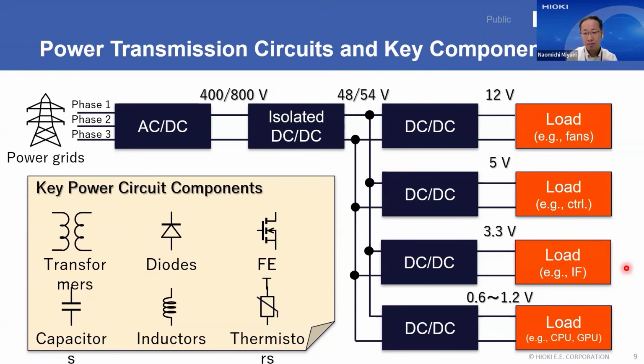This is something that has been difficult to capture with these conventional instruments. From the next slide, I'll walk you through the evaluation of components under real operating conditions, focusing on power inductors, starting with why, and then covering how to select the right instrument for this evaluation, and also some tips to achieve accurate impedance measurement or loss analysis.